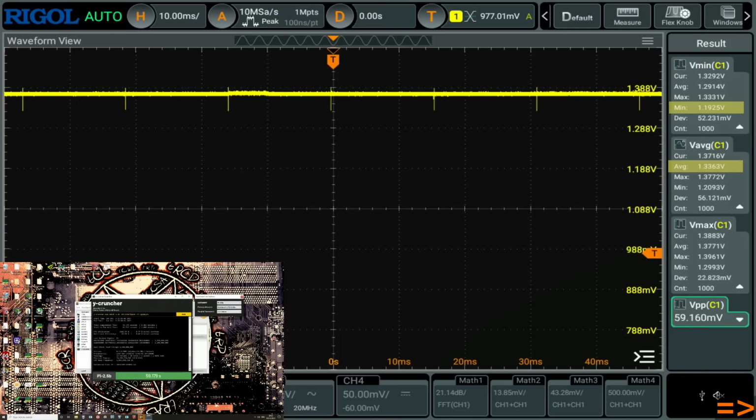That's the other thing you have to consider: if your CPU goes from pulling 10 amps idle to 250 amps load, then yeah, you're going to see a really big V-droop on mode 8 LLC. But if your CPU goes from pulling 100 amps to 150 amps, you're going to see like 100 millivolts less V-droop than a 13900K does. And so a feature like the load line saturation becomes somewhat less useful because there's just a much smaller gap between your idle and your load voltage.